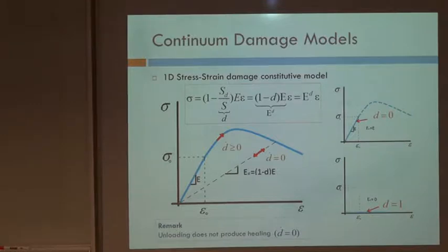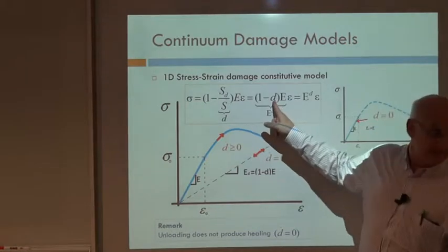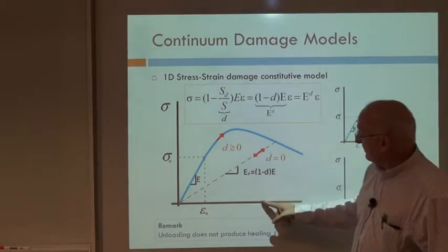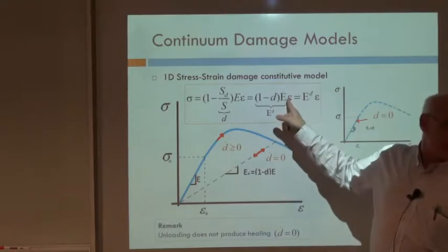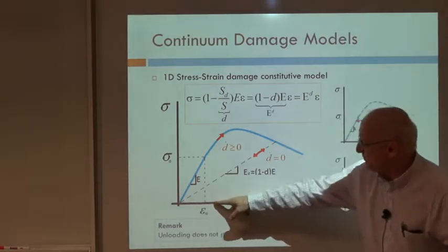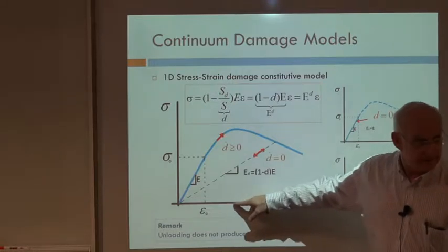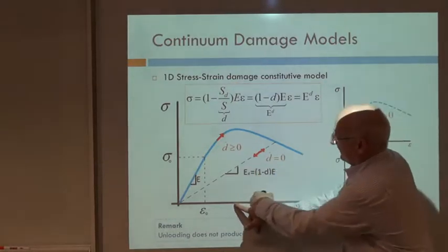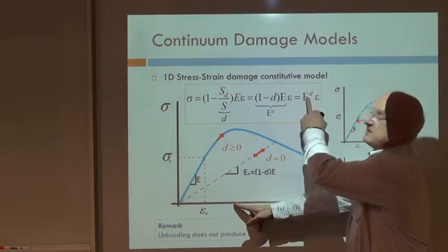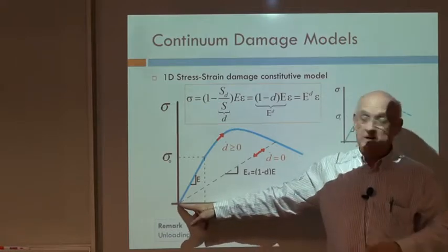We'll see. How could it be that if the stress is zero, the strain is zero, if there is damage? Well, look at that. Imagine that during this process, we cannot vary this factor. What I'm doing during this process is diminish the strains. I'm controlling the strains. The history of the strains was this one, I stretched up to here, and at this point I reverse the strains, and I go into that. In the reversal, I see that this is kept constant. But what happens when I arrive back to this point in terms of the strains? How much are the strains?